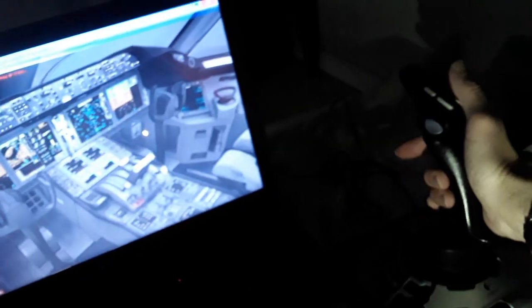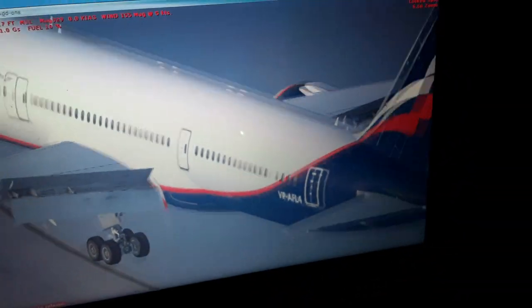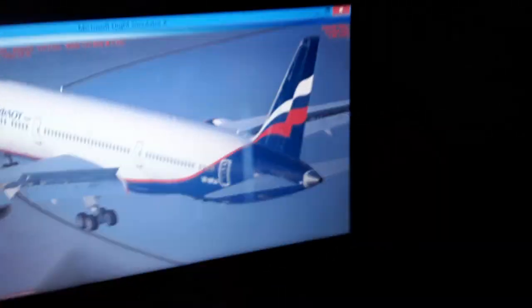When you make turns or climb or descent, you give an order for G load limit that reflects the flight control surfaces identically, proportionally to the G loads you want to do. I'm not sure about the limits of the Boeing, but when you move the flight controls like this, you also have an order for the flight control computers, like in the Airbus, in the newer Boeing 787. So you can see how many degrees you pitch the tail over here, the elevator, for flying to balance the aircraft in the flight conditions.